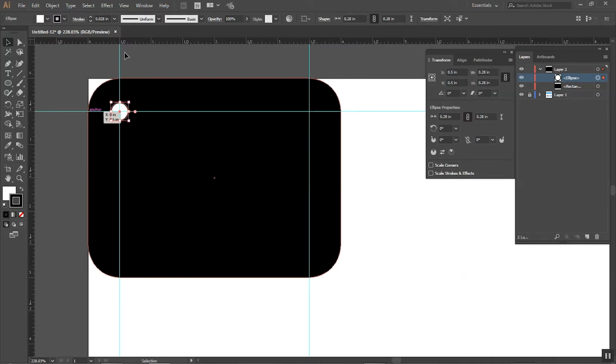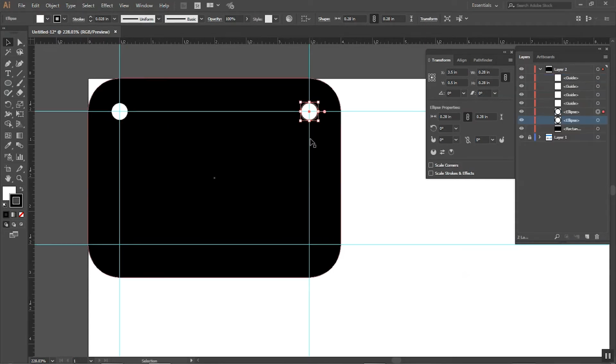If I find the anchor points, because these are circular fillets, I can confidently say that's the center of this radius. Now when I click and drag by holding down Alt, I can snap to these reference points. You'll see it says intersect. So that's good. And then I can just keep doing it, Alt.